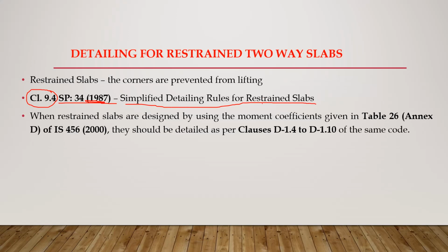These rules are again based on the clauses D1.4 to D1.10 of IS 456 code. So clause 9.4 of SP34 and clauses D1.4 to D1.10 of IS 456 are the same.